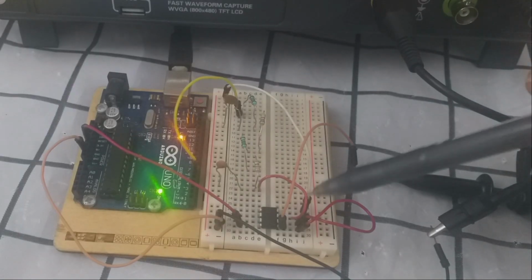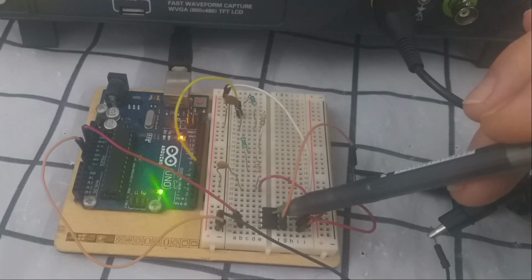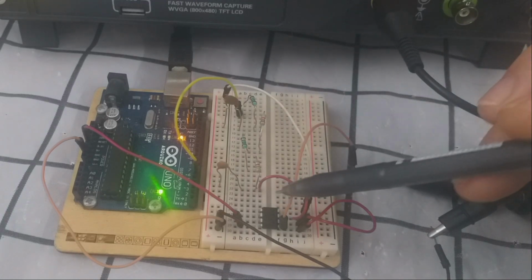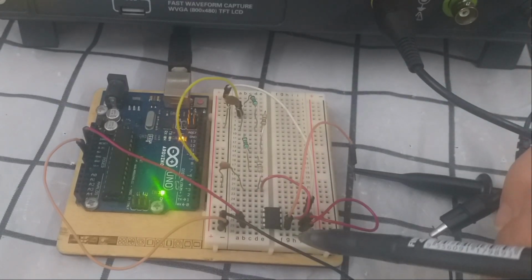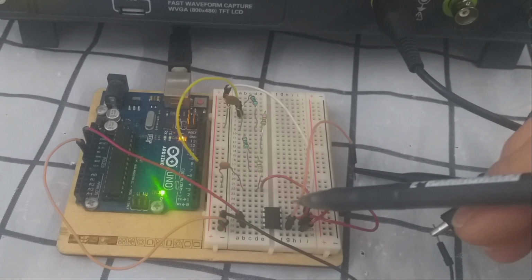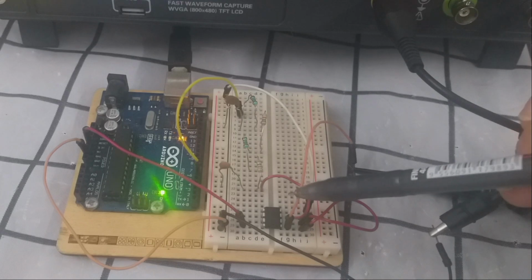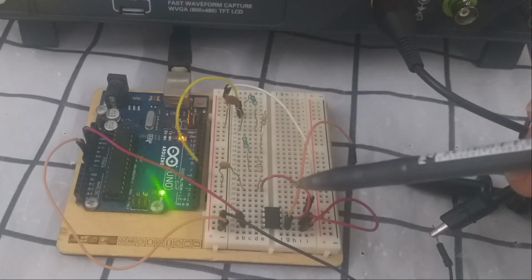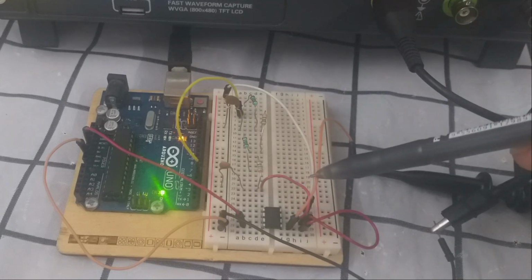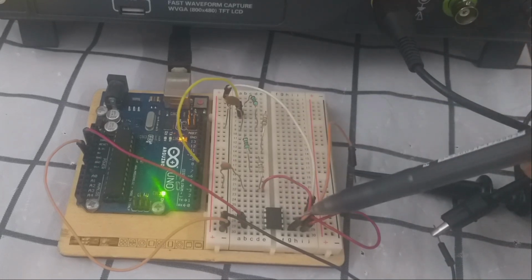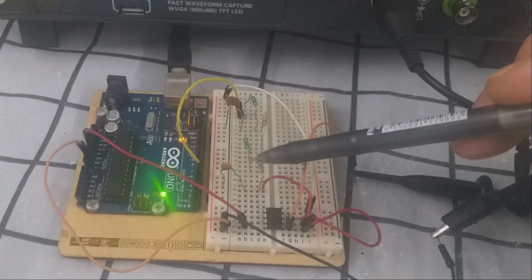So now we can go and implement the circuit. Okay, guys, here I already connected our LM op-amp on the breadboard, and I'm sorry if it's not clear. The op-amp is upside down, so the notch is here, which means this is pin number 1. Pin number 1 is shorted to pin number 2, and this is our output, connected to the oscilloscope. Pin number 3 is the input.